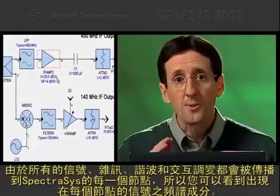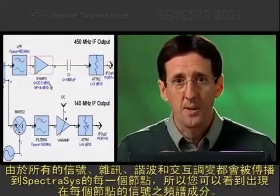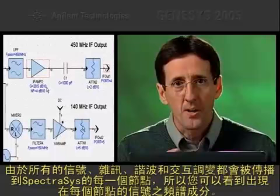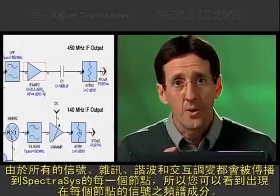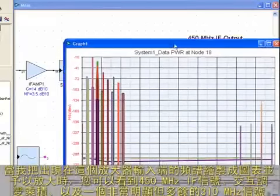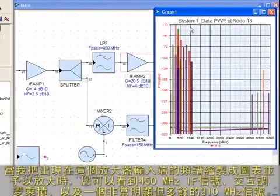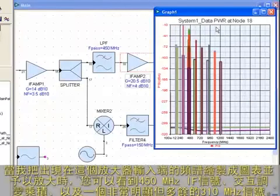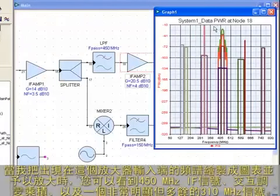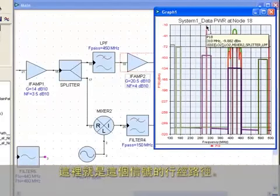I'll click Show to highlight the problem component. Since all signals, noise, harmonics, and intermods are propagated to every node in Spectrasys, you can see the spectral content of the signal present at any node. When I plot the spectrum present at the input to this amplifier and zoom in on the graph, you can see the 450 MHz IF signal, intermodulation products, and a very strong unwanted 310 MHz signal. The path this signal traveled is shown here.